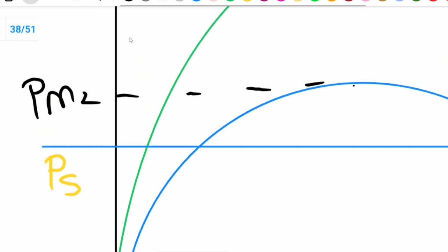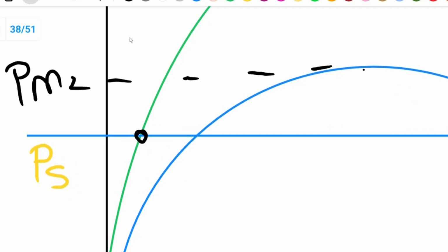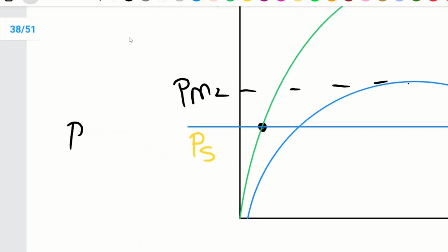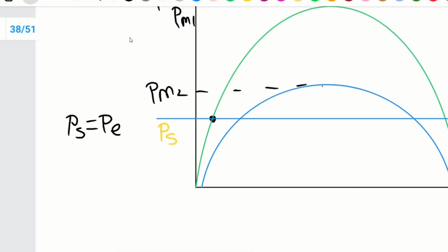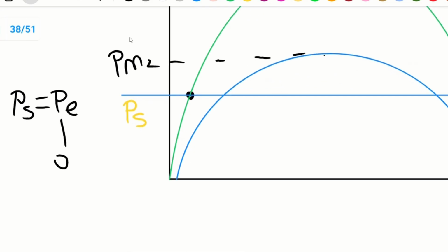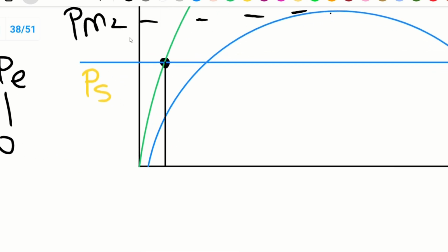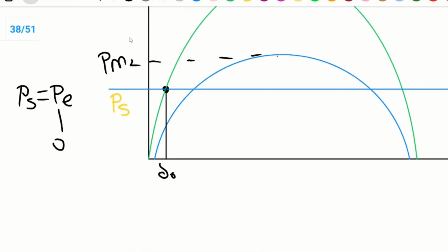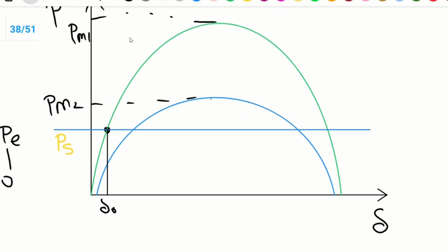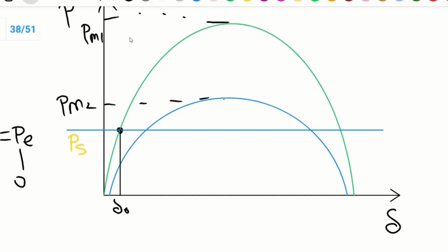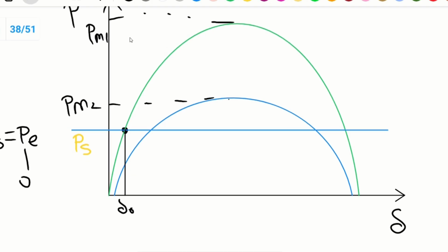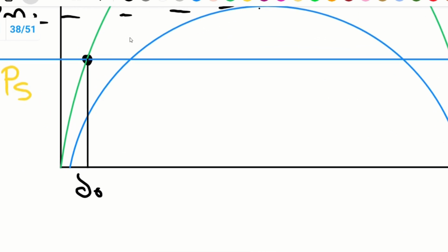So it is operating normally at steady state, operating at this point, and at this point Ps equals Pe. And when the three-phase fault has occurred, the electrical power will become 0. Now let's say the angle is delta naught. The rotor angle will not change instantly, so the angle between the rotor and the synchronously rotating axis will not change instantly. After the fault has occurred, the rotor angle will change gradually. So suppose at this point, delta CR,